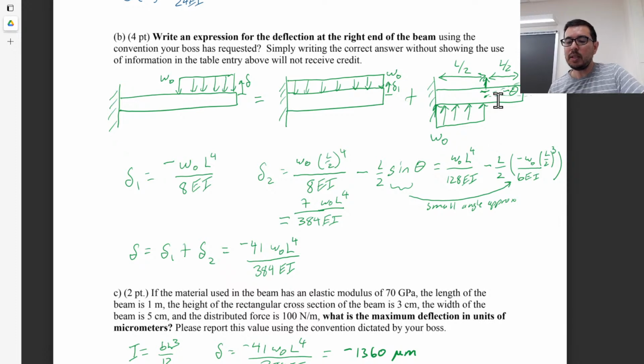So that means this region you can think of as perfectly rigid. The deflection that you have from here to here, this last L over 2, is essentially to say, use a small angle approximation. It doesn't matter if you take the hypotenuse or this one, but essentially you have to say, what's that angle? And I multiply by that length in order to figure out how much it's shot up.